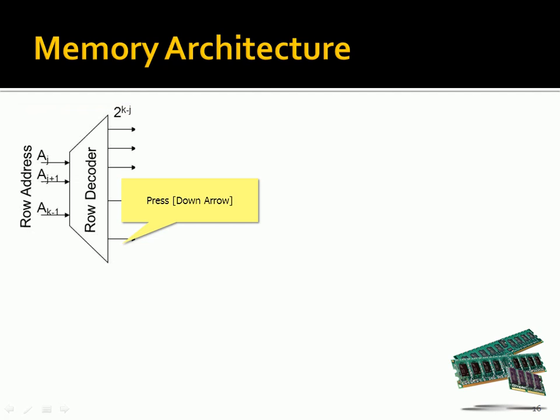Let us see the general architecture of memory organization. Memory is basically formed in a matrix fashion. In order to locate a particular cell in a matrix, we need to address it on two sides: row-wise and column-wise. So the CPU address generated by the processor needs to be split into a row address and a column address. Combining these gives the total address.